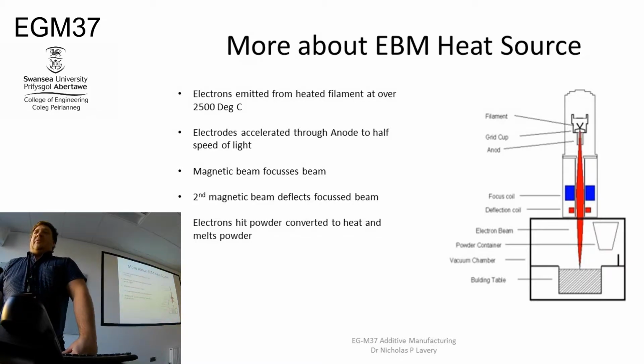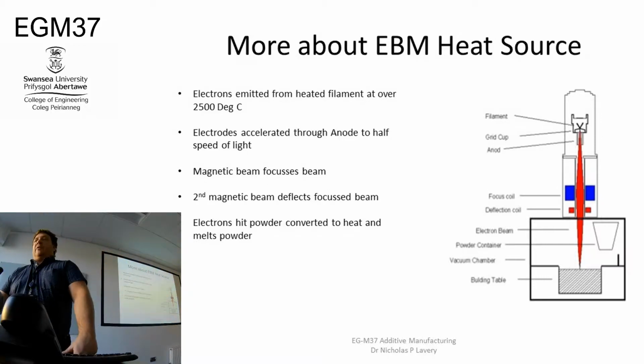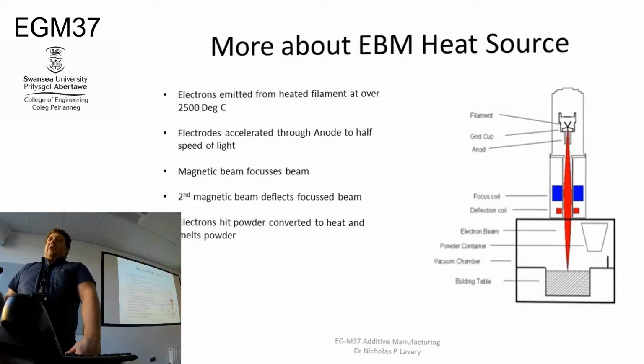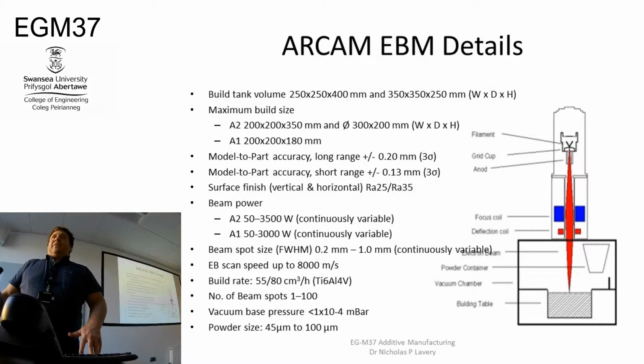Okay, so what we did see with the ARCAM EBM system was that there are actually two containers, one on either side of the powder bed, and both of them tip out together, and you have a spread from both of the hoppers.